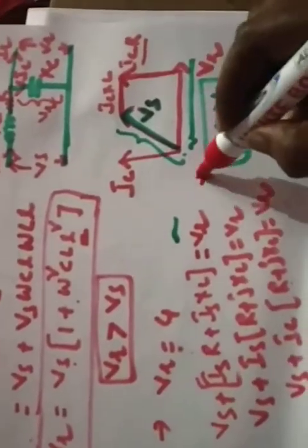So this is the statement of the Ferranti effect. How is this Ferranti effect coming out? Because of the capacitance existence. So the current IC plays a predominant role while developing this type of Ferranti effect. That's why we can also call it the charging current effect.